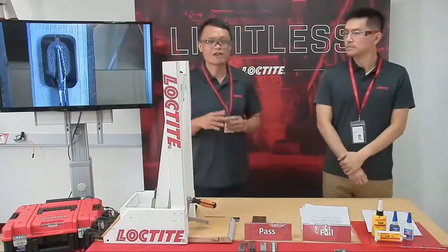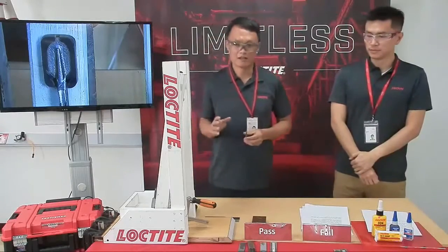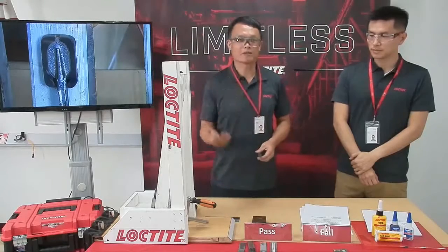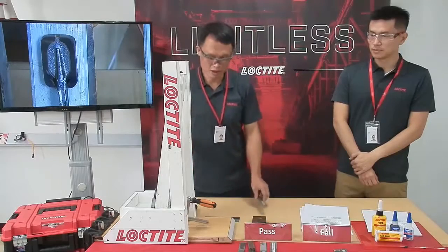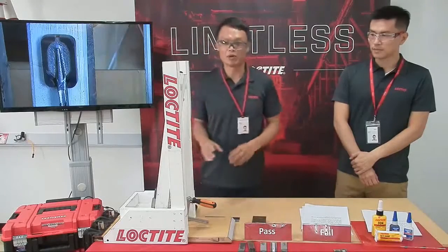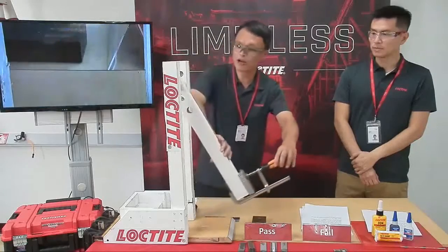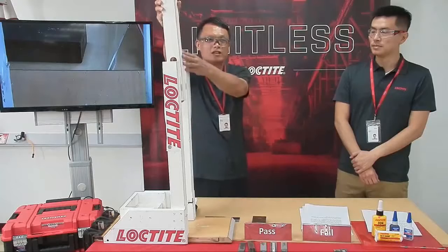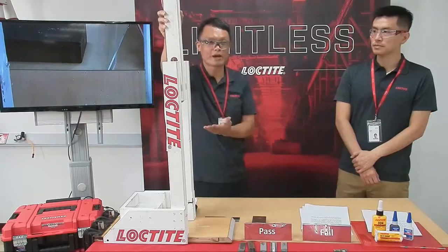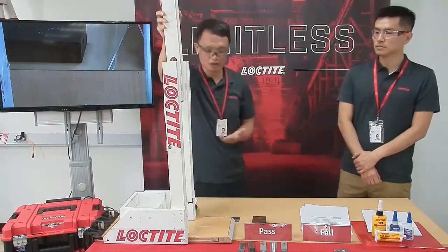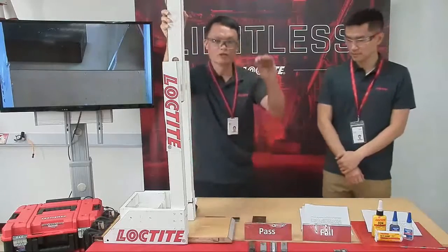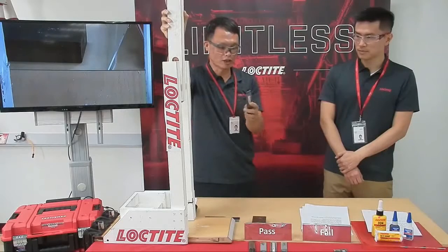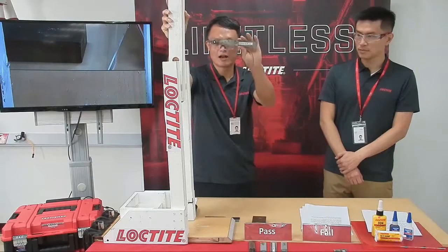Okay. Now we have completed the first round of tests, and the standard CA is out of this game. Now we have to step up the test by increasing the impact energy. To increase the impact energy is very simple. The way I did it is by increasing the swing angle from 90 to 180 degrees, which doubles the impact energy to the joint. Let's come back to the first candidate, the welding specimen. This one in my hand is a 4 spot weld joint.